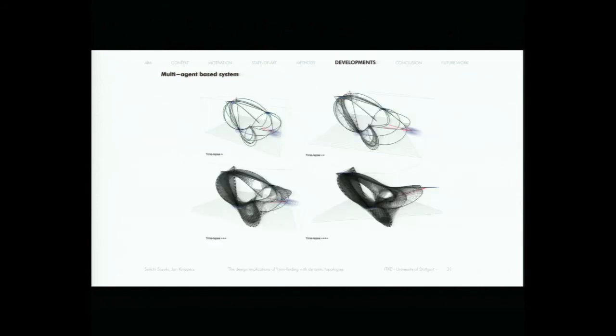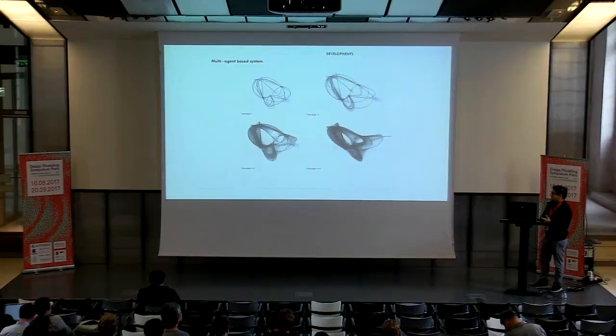All the children from one parent shape a family, and each family represents the network model of an elastic rod. At the same time, the behavior of children is activated in order to search for potential partners based on distance constraint and the range of view of the agent. As soon as a potential partner is found, a tensile connection is created and the equilibrium system is changed. In this case, the designer has limited control of the form-finding process because it is mainly driven by the agents.